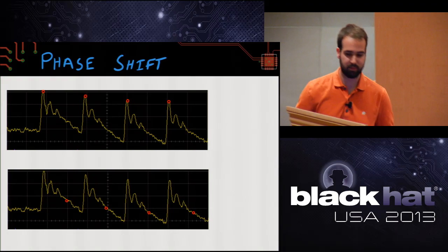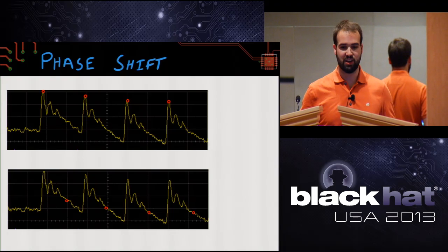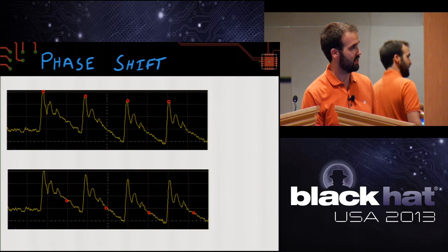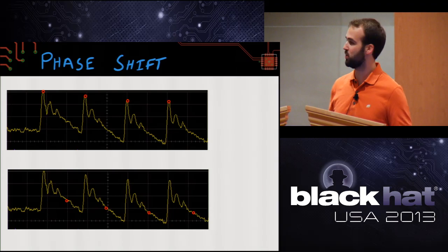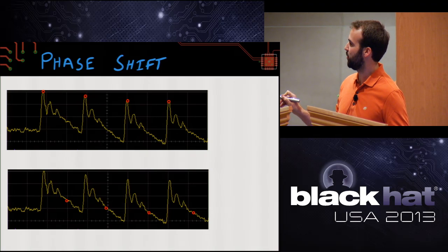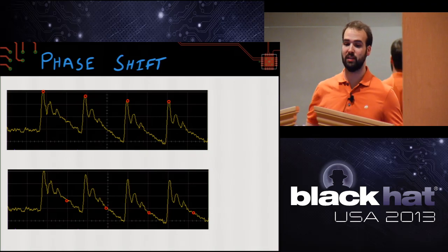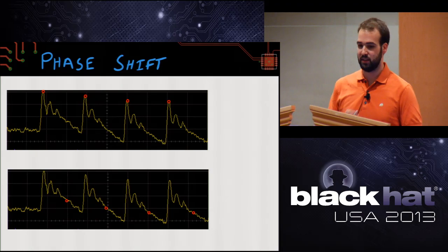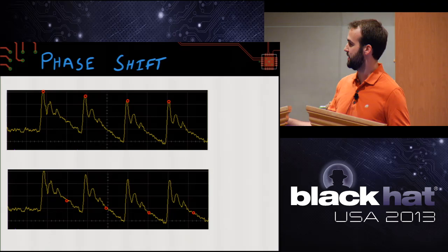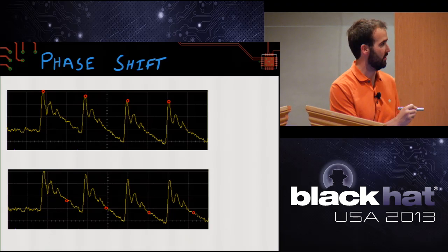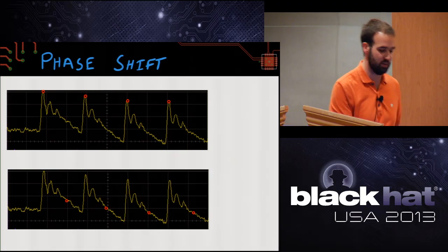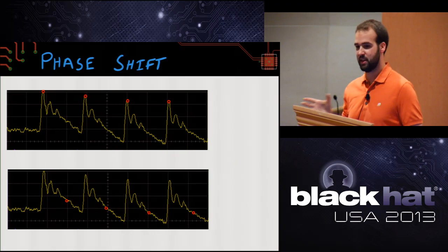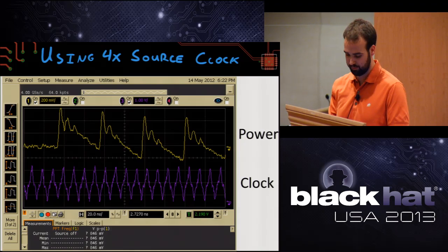The one small change when you're doing this with its sample clock is you need to be concerned about phase shift. We can see in red there's some sample points, so I could say, well, if I could sample here, that's really good. It may be that because of delays in the system, I actually sample at the zero crossings and I really don't get any information, so this bottom one. So you need to be able to control when the sample occurred relative to the device clock.